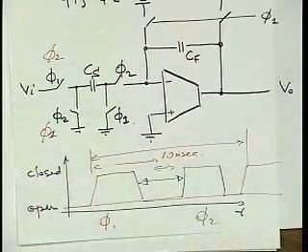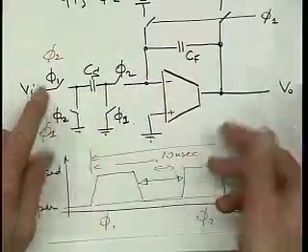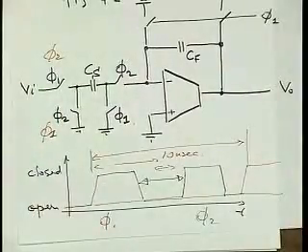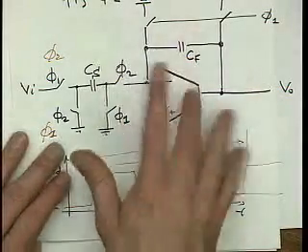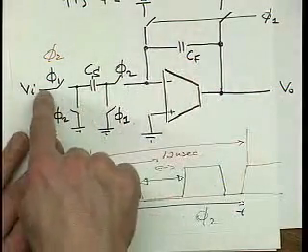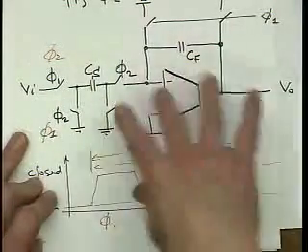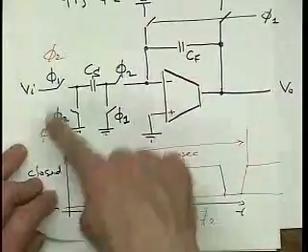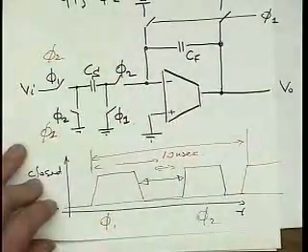And so now this thing with, oh, we don't know where we are starting from, that problem's gone away. And then during phase 2, this one's closed, this one's closed. We just have an amplifier that amplifies whatever we put at the input. In practice, when we cascade these, we like to alternate them so that we don't have a whole bunch of the red case all in series, because all the amplifiers would have to settle in series, one after the other, right? And that takes extra time. So having the black case every once in a while is nice because it breaks the chain.